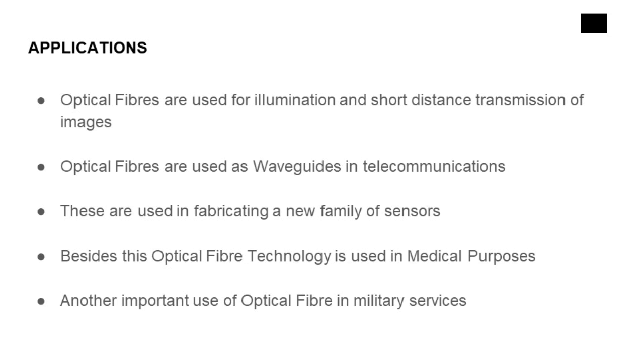Transmission of light via an optical fiber has a wide variety of applications. Now we discuss here some major applications of the optical fiber. First, the major application is illumination and image transmission. How? A bundle of fibers whose ends are bound together, ground and polished, forms flexible light guides. If no attempt is made to align the fibers in an ordinary array, they form an incoherent bundle, in the sense that there is no correlation between the position of the fiber terminations at one end of the bundle and those at the other end of the bundle.